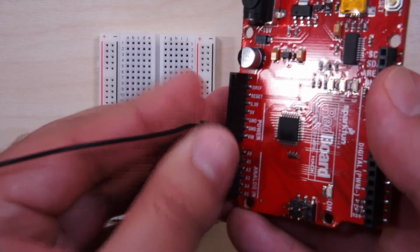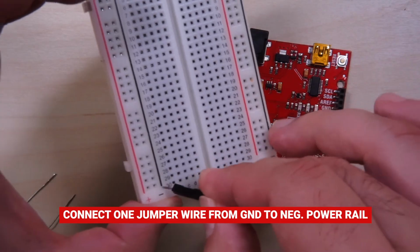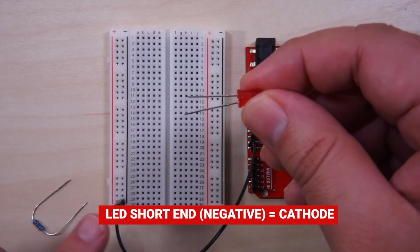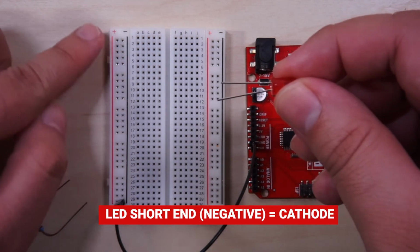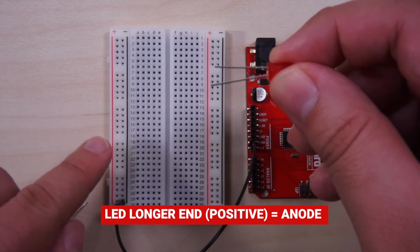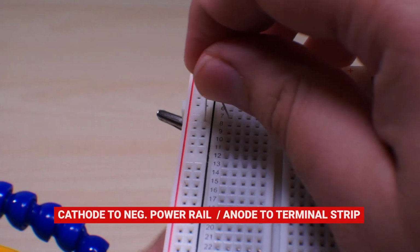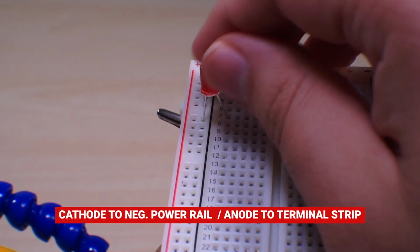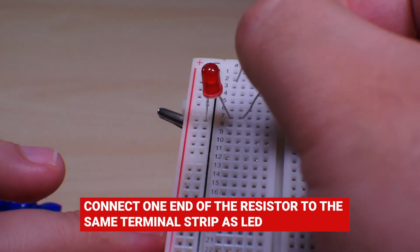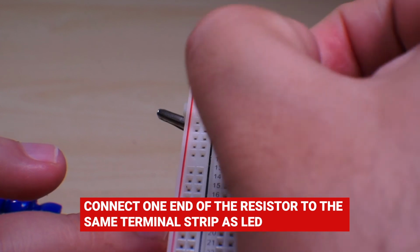Take one jumper cable and connect the ground on the breadboard to the negative power rail on the breadboard. Next, take your LED and connect the cathode or the shorter leg to the negative power rail on the breadboard. Then take the anode or the longer leg and place it on the terminal strip. In the same row on the terminal strip, place one end of the 10K ohm resistor.